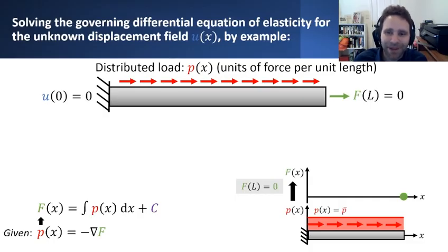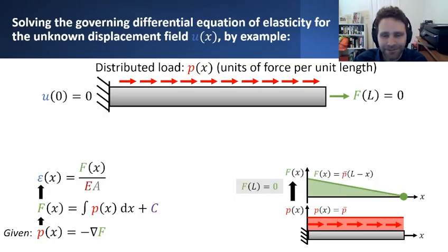And if we impose that boundary condition, then we can solve for this extra constant of integration c in order to figure out how that internal force varies. And noting that this differential relationship integrates some constant function, what we expect to get out of this integration operation is that the internal force varies linearly along the length of this member. All right, well, that makes things fairly easy. We can use our boundary conditions to make that statement of how the internal force varies explicit and unique.